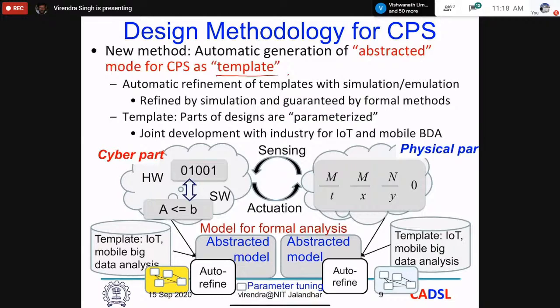So, equivalence checking and model checking are very much used in industry. Theorem provers are not that common because those are not really a fully automated system. They are semi automated. What that means is that you need some manual intervention to guide the verification process. And unfortunately, industry doesn't like anything wherein there is a human intervention.